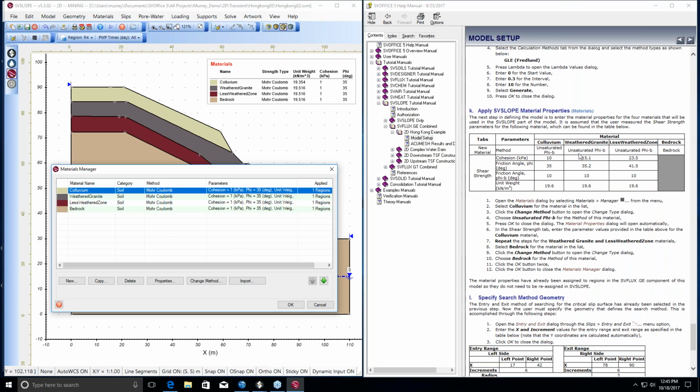What we want to do is change it to account for unsaturated strengths, because the problem in this model is that Mohr-Coulomb does not consider the effect of suctions. So if you ran the model with Mohr-Coulomb strength, you would see no influence of the changes in suctions up near the ground surface. To include the impact of suctions on shear strength, you need an unsaturated constitutive model.